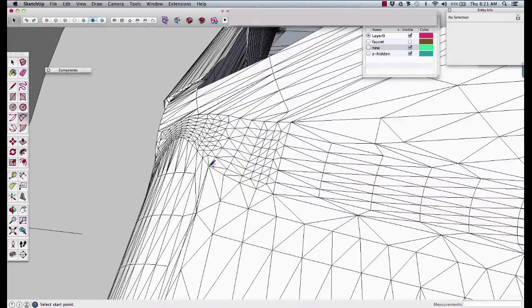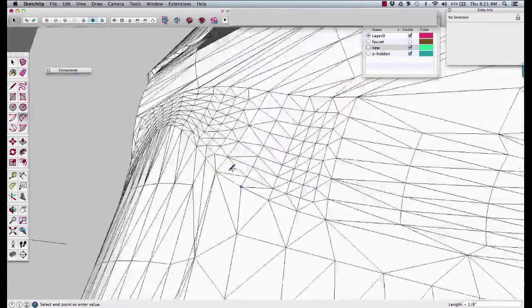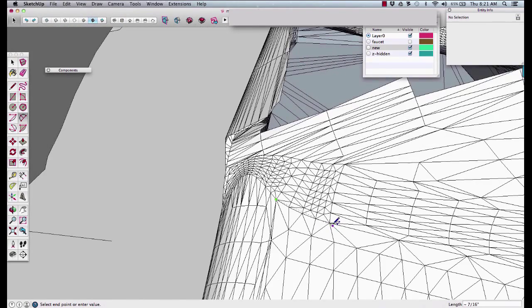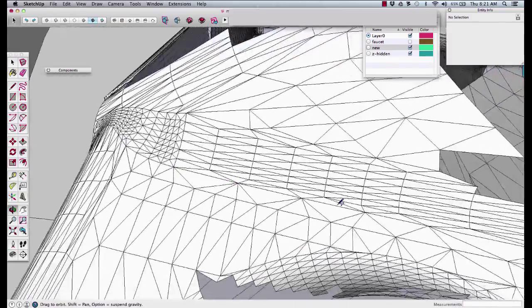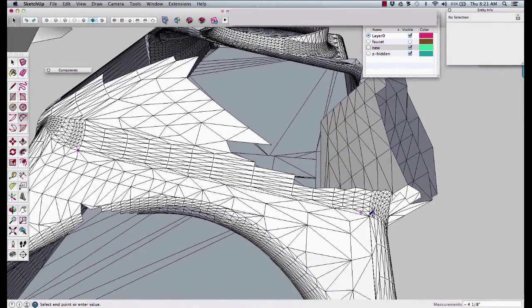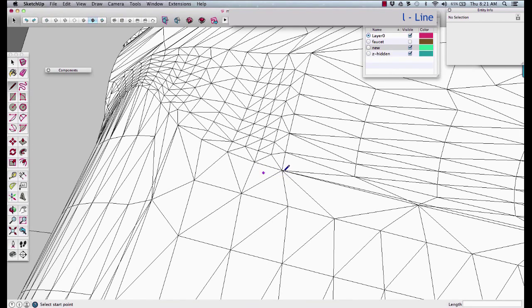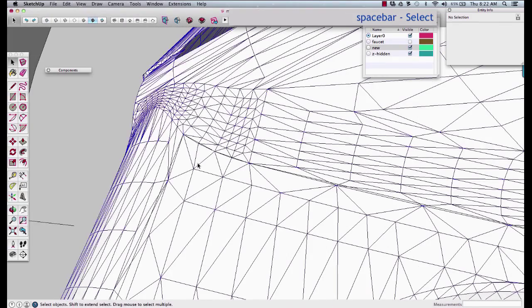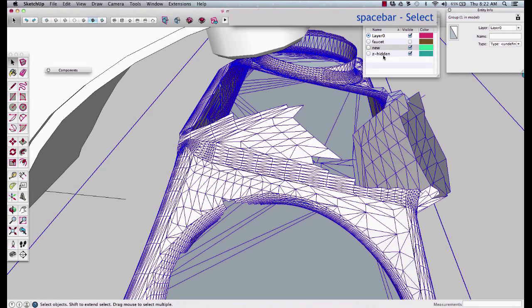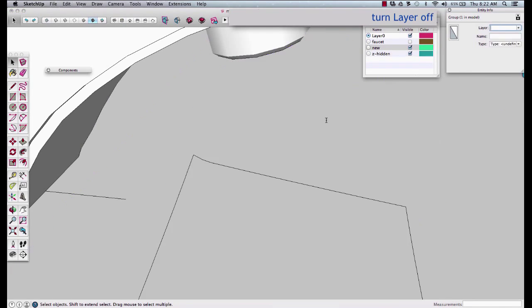And finally, an arc. Now this one, there's a compound curve happening. There's a curve from there to there, and then there's a larger curve from here. So I'll start the curve from here to here, touch it, and draw just 2 line segments, L, to connect it all up. I'm going to select this and put it on the faucet layer so we can turn it off.